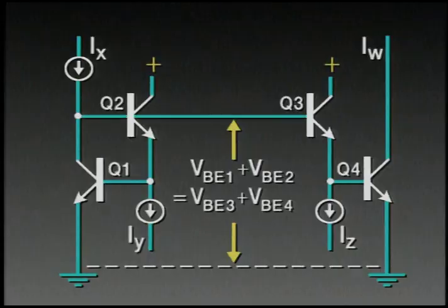In fact, we don't really need the operational amplifiers. This is a more highly integrated form, or really perhaps what I should say is this is the topology that we might start with if we were to approach this as part of a monolithic design. We still have the same four transistors. They're connected in exactly the same way as before, but we don't have the luxury of operational amplifiers to drive the various junctions.